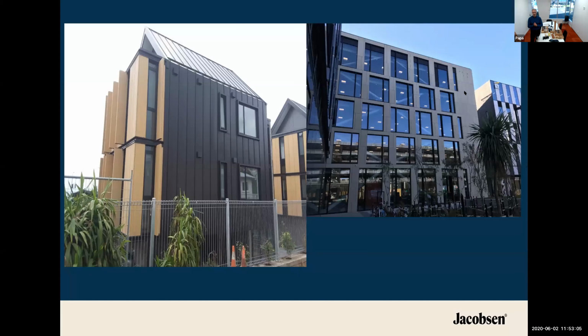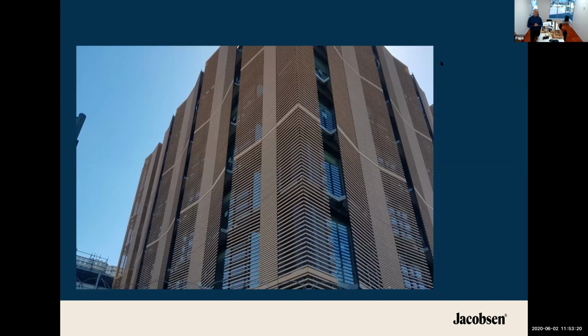The building on the right there, the office block down at Christchurch, the panels across the top are actually 3 metres by 800, and then the rest of them are just various sizes to suit. Just fixed top and bottom. There's no mid-span fixing. Again, Phil, great. We can do some screens, some baguettes, they're called, over a glazing system.